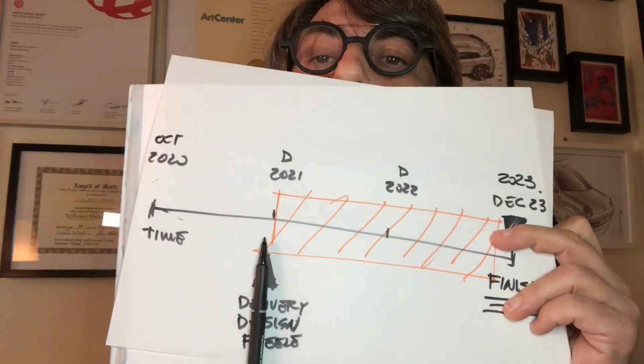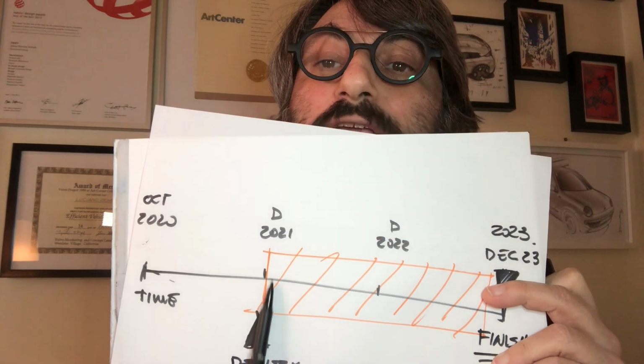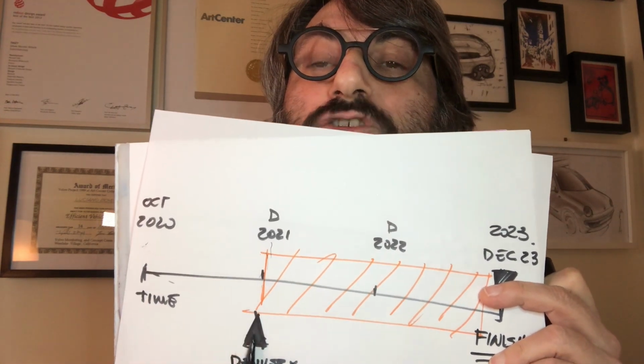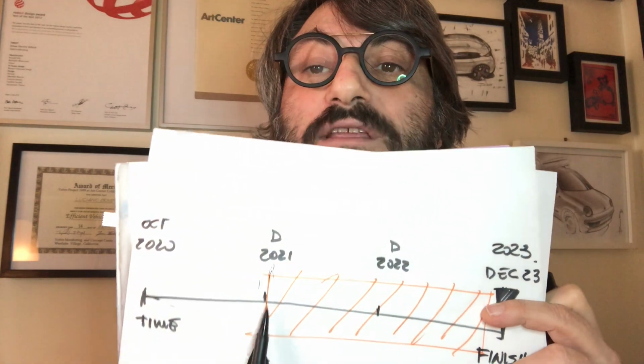And it's called design freeze here. It's called design freeze because when we give all the virtual model, the full-scale model of everything, it means that it's frozen. We cannot change anything anymore. Why? Because everything has been developed together to make sure that the project we made is cost efficient. That's why we cannot change, because as we move something, that cost equation will change. And because we are talking about a production project, you cannot do that.